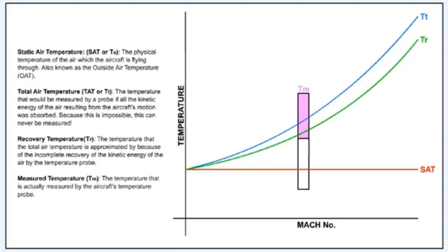Air temperature is one of the basic parameters used to establish data vital to the performance monitoring of aircraft engines, for example, thrust settings, fuel-air ratio settings, etc. The ideal temperature to suit these requirements is that sensed under static conditions at various flight levels. This temperature is called variously the outside air temperature or static air temperature, SAT.